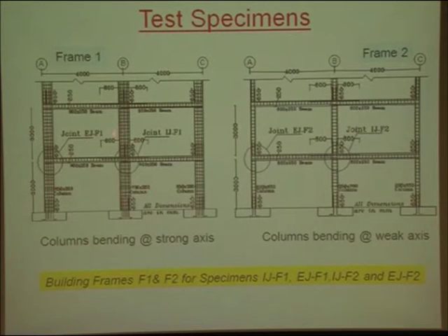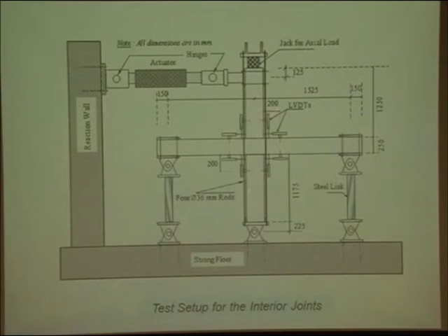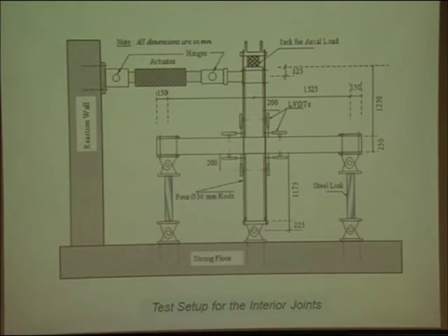And we can take the entire building, or we can take only a small frame of the building to simulate the building, put it in the lab, at full scale, and study its response under earthquake load. And we have the facilities in the materials and structural lab to do that. This we did. So this is a reaction wall where we can apply the earthquake load. I can simulate the earthquake. It is not really an earthquake, it's quasi-static, and we apply it gradually to take measurements.